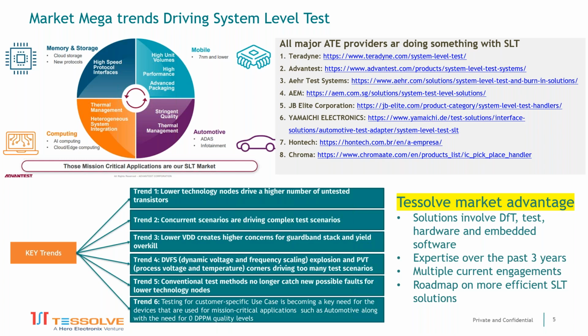And what they're saying is through this, they are starting to find untested transistors that weren't tested from their normal ATE development. They can find them in the SLT. And then you've got a choice. You can either start to do high volume SLT to find those bugs or those faults, or you can take that fault and work out how you can then detect that fault via structural test. But what they're saying is that there are untested transistors from that analysis. Does that make sense? Yep, it does.